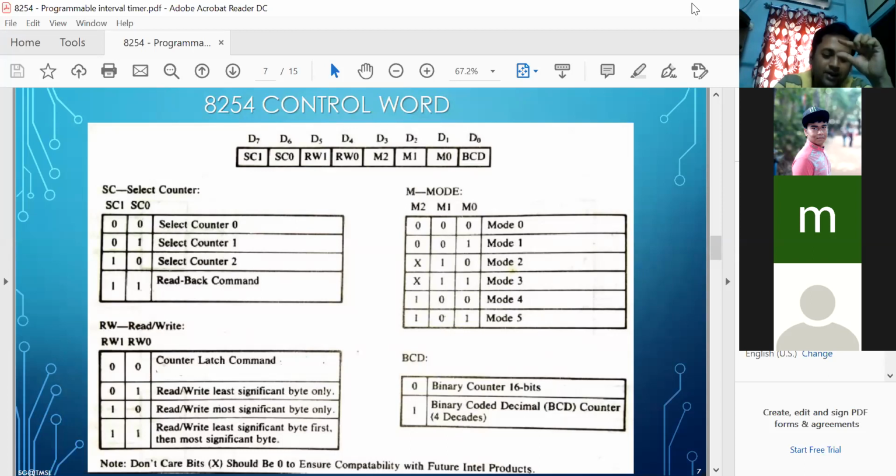So when you press the button, the signal is affected, and it is not stable as soon as it is given. It takes a certain amount of time to reach a stable condition, otherwise the signals fluctuate. This fluctuation is called bouncing, and the problem is called the bouncing problem.